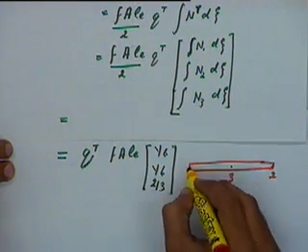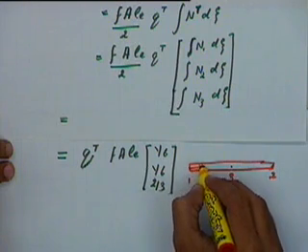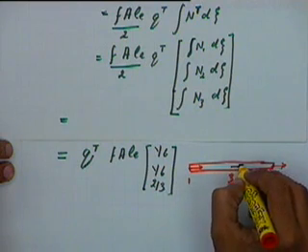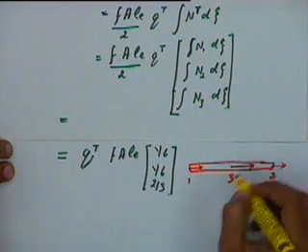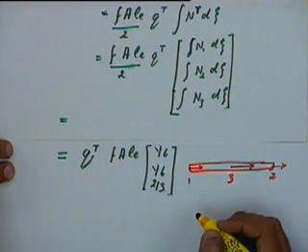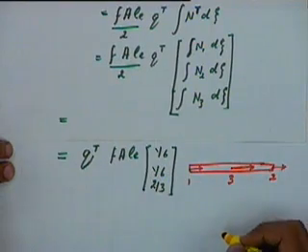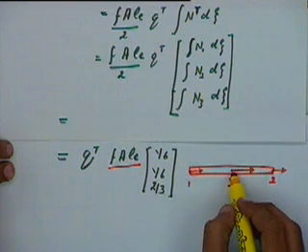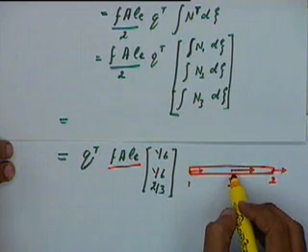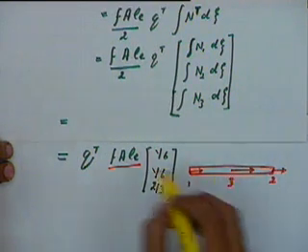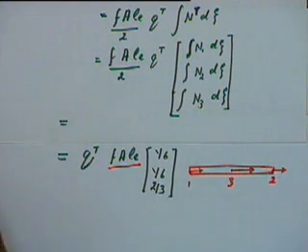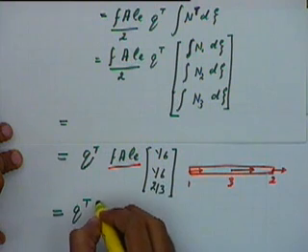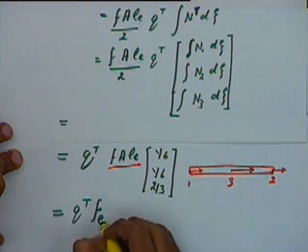So, what we can say is effectively 1/6 of the body force is acting here, 1/6 is acting here and 2/3 is acting over here. Well, the total body force acting is this, which is divided in this ratio at the three nodes. And this will be equal to Q transpose multiplied by, let us say, the body force vector for the element.